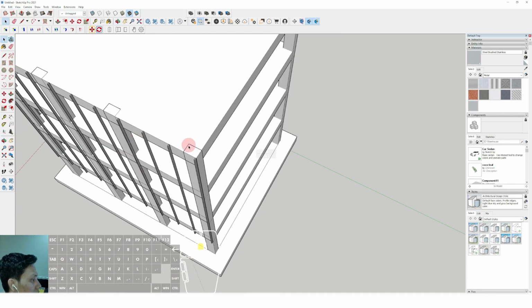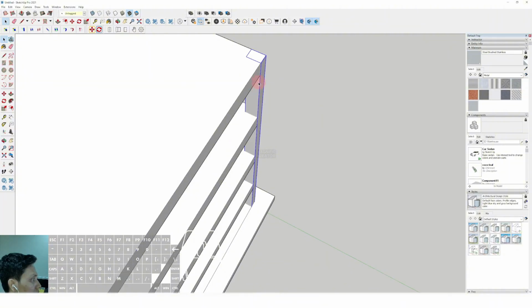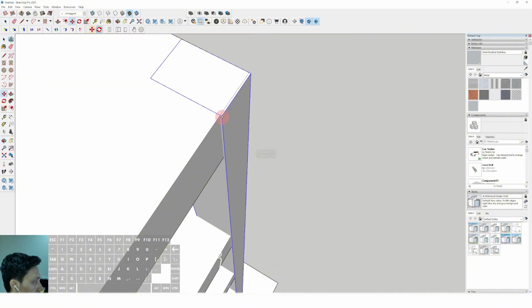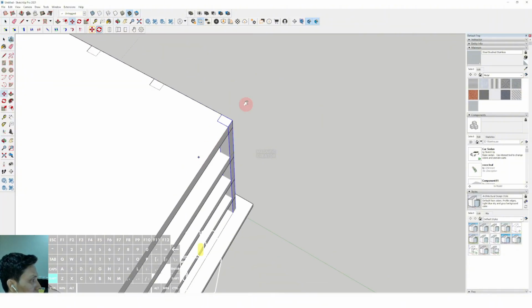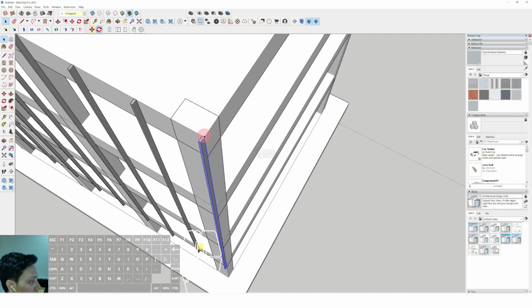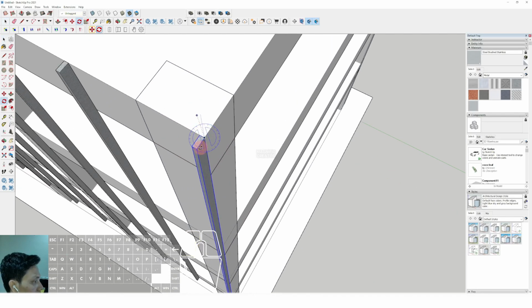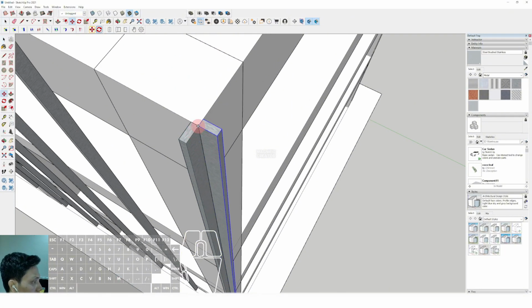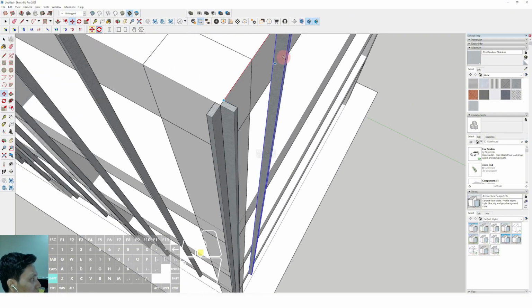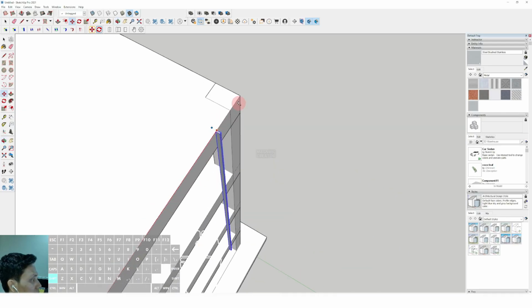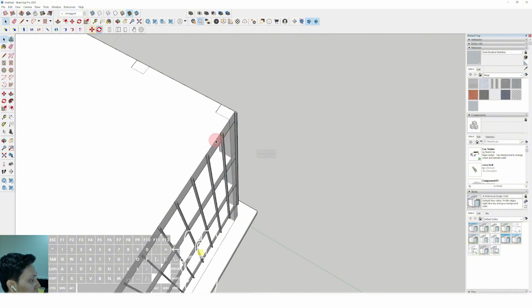Now we can fix the column positioning in here. Now we can rotate 90 degree and select move, tap control, and place to the position. Then we can type 10 slash and enter.